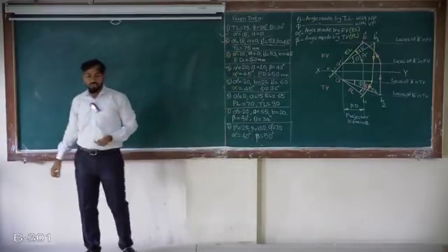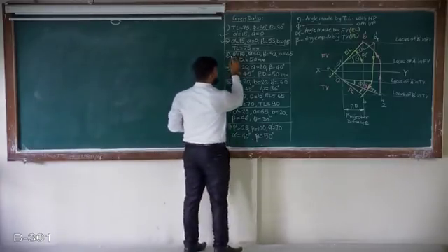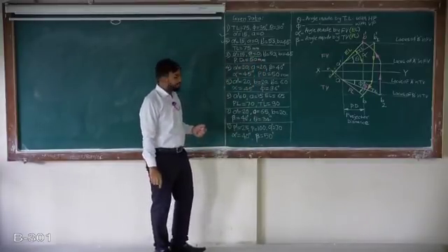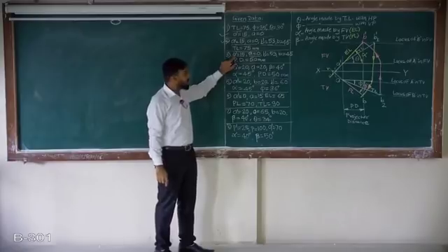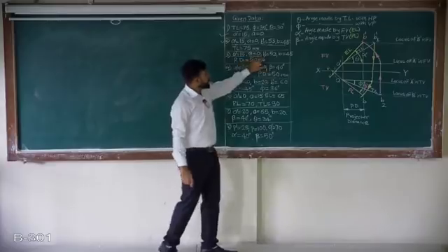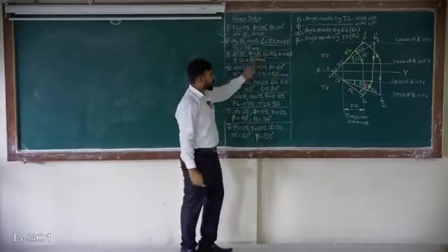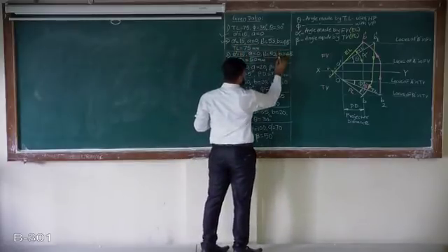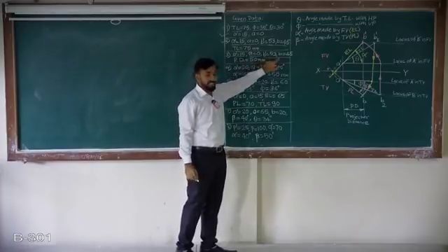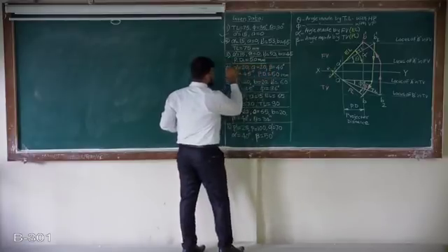Okay, now question number 3. What is given in this? A dash is 15, A is 0, means simply point A of line AB is 15 mm above HP, whereas the same point A is in VP. B dash is 53, B is 45. All given data, the first 4 parameters, are common. The last parameter is changed to projector distance.